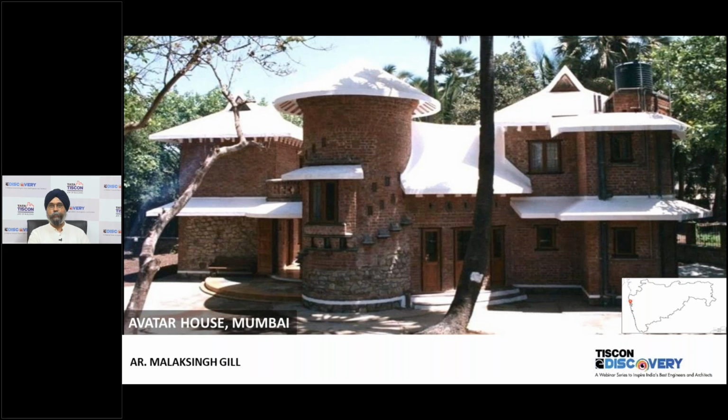What will stand out over here is to see that in a place like Mumbai, which has high rainfall, the walls are not plastered. Besides, if you look at the roof, you will see the slab. It's an RCC slab, which has these filler materials, which are basically double Mangalore tiles, Mangalore pattern roofing tiles, kept one above the other and occupying the lower part of the slab.